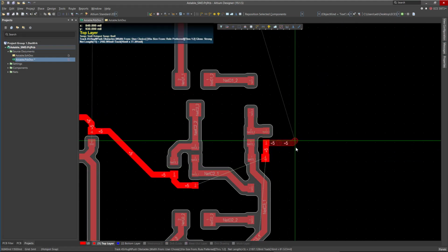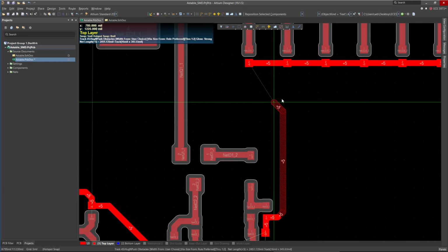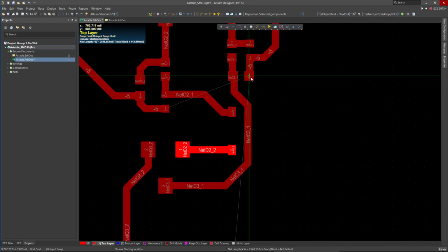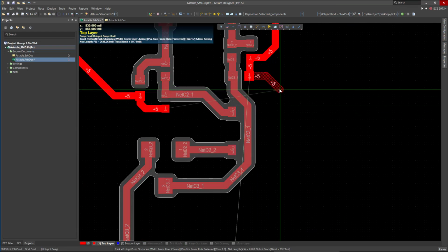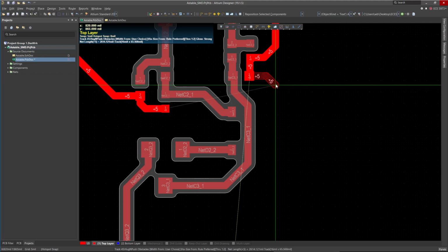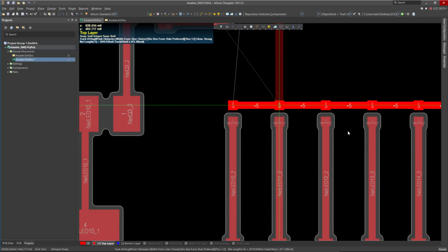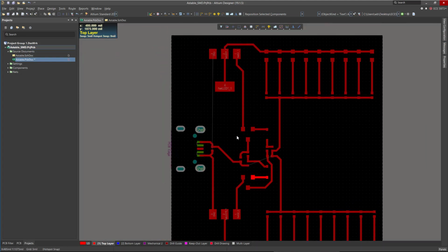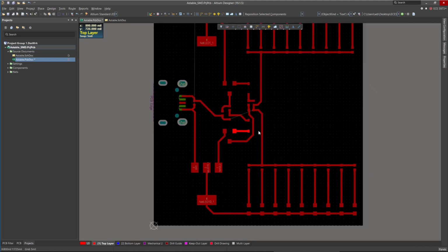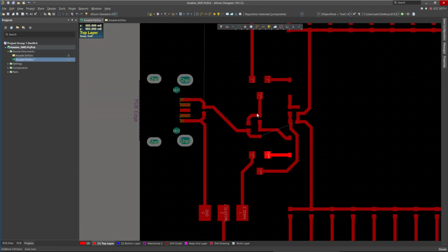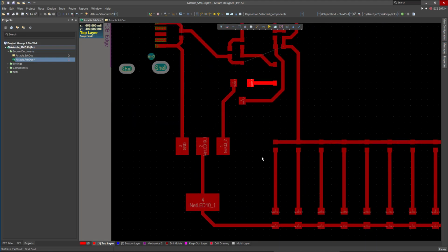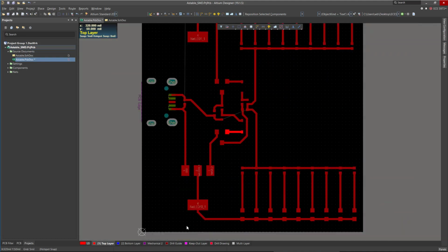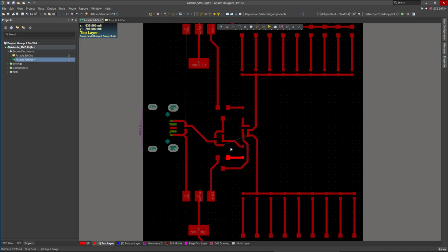So we have 5 volt in here. We can take this all the way here, and also we have 5 volt in here. All the way down here. Okay. What's left? We have one ground line, and we have this 5 volt. So this 5 volt, what we can do, let's do via for this, but be careful now.